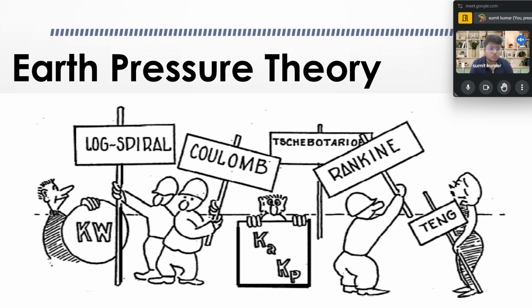has added this for the cohesive soil, and we also understood some of the important aspects of the tension crack, that how tension crack develop. If tension crack is not there, what are the differences in the value of the stresses. We also come to know how much the total stress could be acting on that wall through the backfill, in the active and passive conditions, and we also understood the unsupported length at the same time.